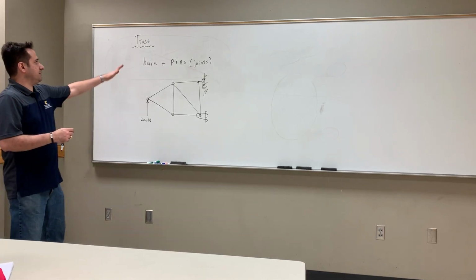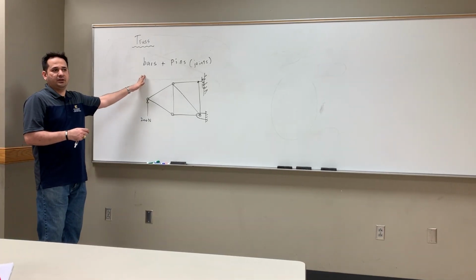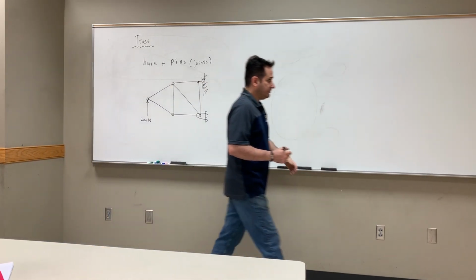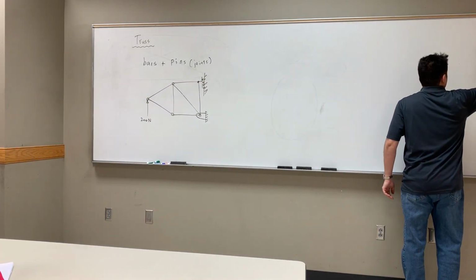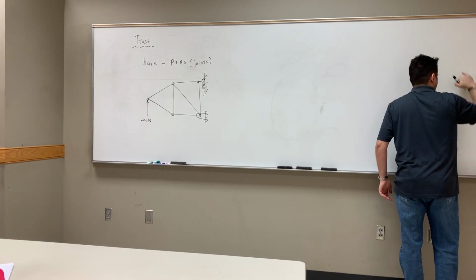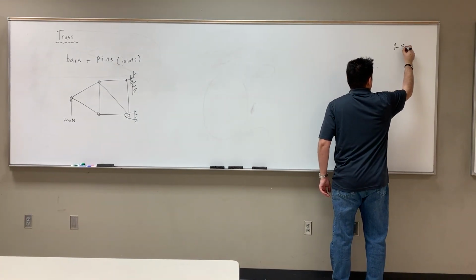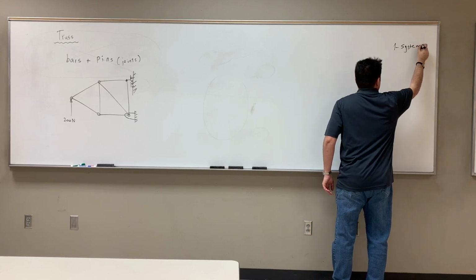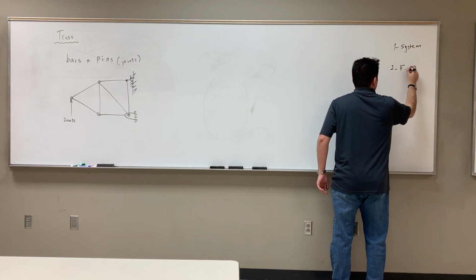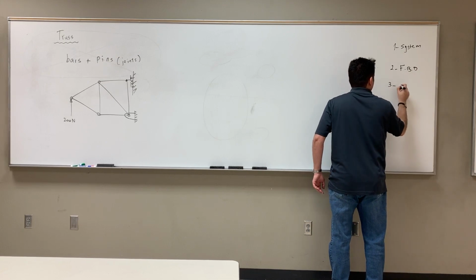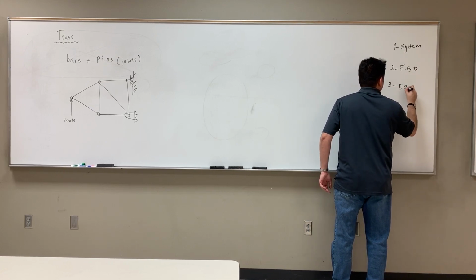Right? Today again we have a 5-step algorithm, but we try to simplify this to a particular subclass, called the method of joints. So step 1 was choose the system. Step 2, draw FBD. Step 3, write the equations.